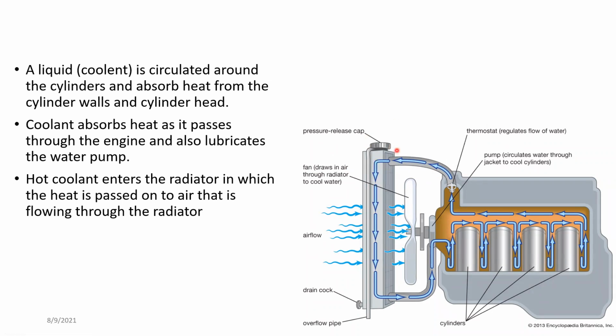During operation, if any air pockets are generated, because of the high temperature they always try to move up, against gravity. If the pressure cap is not at the highest position, these air pockets will gather in some other place, reducing the effectiveness of the cooling system, or it may even end up damaging the engine itself.